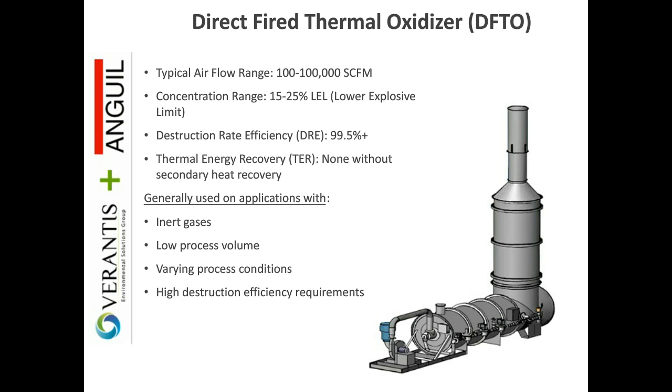Again, these are the opposite of the RTO in terms of energy efficiency. So really where these tend to be applied are in chemical plants, like a batch application with very high loadings, or an inert stream where it's either nitrogen blanketed or inerted with another compound. And again, there is no internal heat recovery, so if there are low VOC loadings, then you're looking at a very large gas bill at the end of the year.